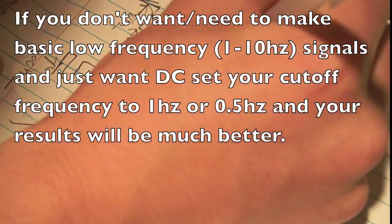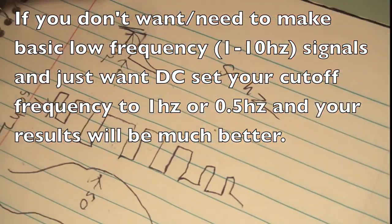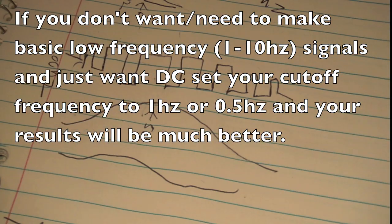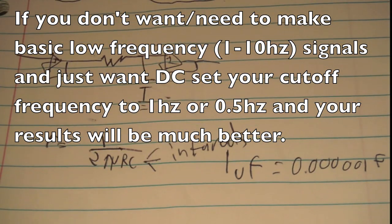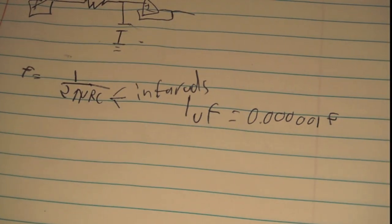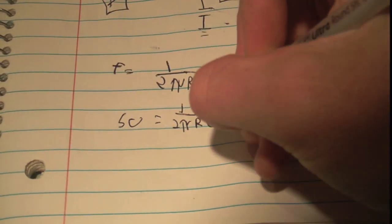In my case, for the cutoff frequency, I'm going to select 50 hertz because it's a multiple of 500 and it's a nice, neat value. Okay, but you could select anything you want. So I'm going to show you what to do once you've selected your cutoff frequency. So this is going to work for anybody. Okay, so our cutoff frequency, we know it's 50 hertz. So we're going to write 50 equals 1 over 2 pi RC.